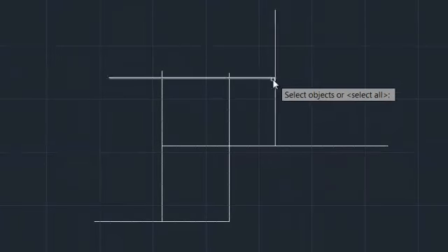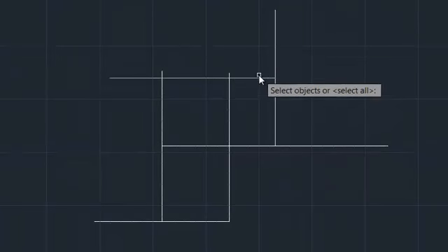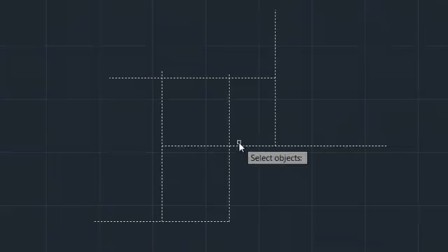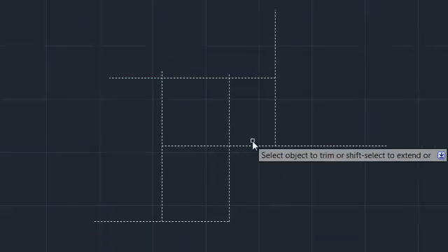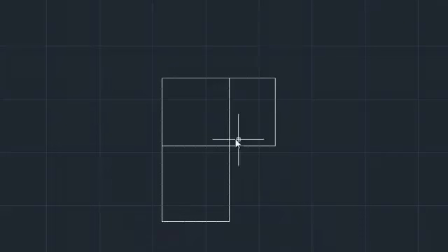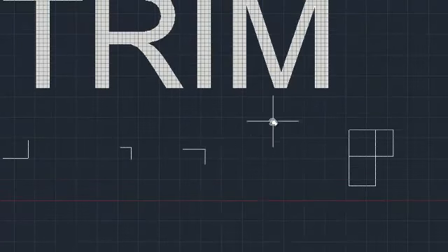If you've got a lot of trims to be made, sure, you might say, I want to cut this bit of the line off first, so I'll select that cutting edge, then I'll select trim. I might want to get rid of this bit of the line, I can select that cutting edge and select trim, but that's a bit time consuming. As a shortcut, you can select everything and tell AutoCAD that you want every line there to act as a cutting edge. Now just select the lines that you want to cut, and that's done. Hope you found that helpful.